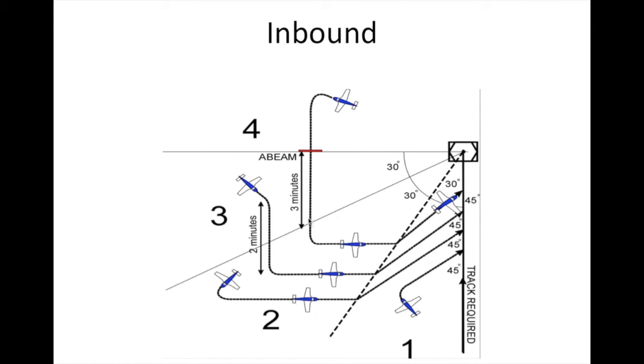And if you are anywhere else higher than 60 degrees, what you're going to do is fly in the opposite direction of that inbound, which means here, if 180 inbound, you're going to fly 180. You're going to fly straight south. Once you're 60 degrees away, you're going to turn 90 degrees left until you're 30 degrees away, and then at that point you're going to turn to intercept it at 45 degrees.